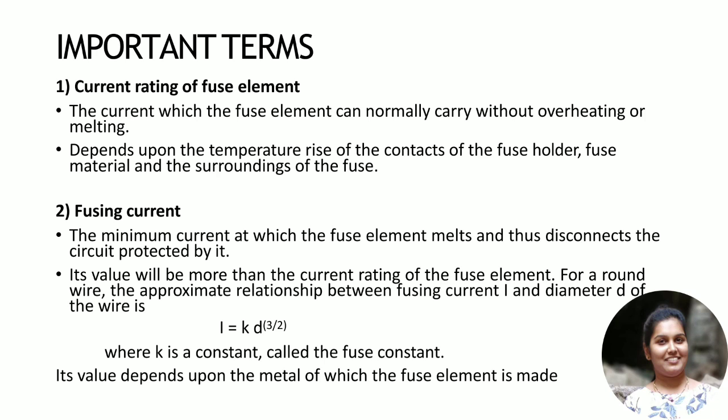Coming to the important terms like the ratings of a fuse, or the points which are to be kept in mind regarding the selection of a fuse, are these points. We'll discuss these things in detail. First, we'll take the current rating of the fuse element. What is meant by current rating of the fuse element? The current rating which the fuse element can normally carry without any overheating or melting is the current rating of the fuse element.